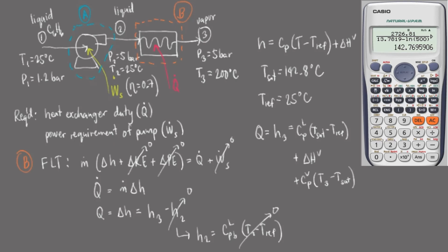Okay, you have to be very careful in accounting for all of the enthalpy terms. With our developed equation, we have to look for the values of 3 parameters. First, the heat capacity of liquid benzene. Second is the enthalpy of vaporization of benzene at the saturation temperature. And finally, we also have to look for the heat capacity of benzene as a vapor.